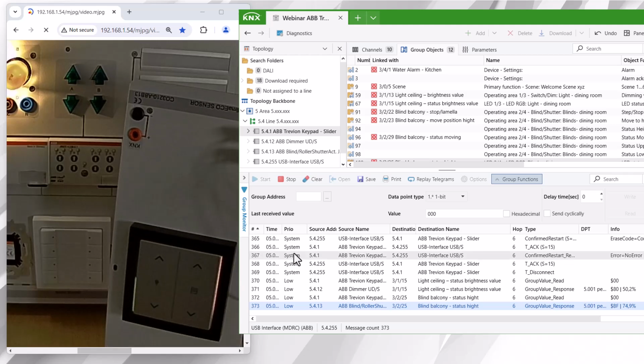So this is, of course, not only basic knowledge, I think a little bit more, but I think you need this function so that a customer can always see the correct status of the dimmer, shutter, or switch actuator, and so on. This also works with other panels like the Smart Touch or our Room Touch. So this is a basic function of KNX, but not everyone knows this possibility, how to update the status of the LEDs after downloading a control element or a sensor.